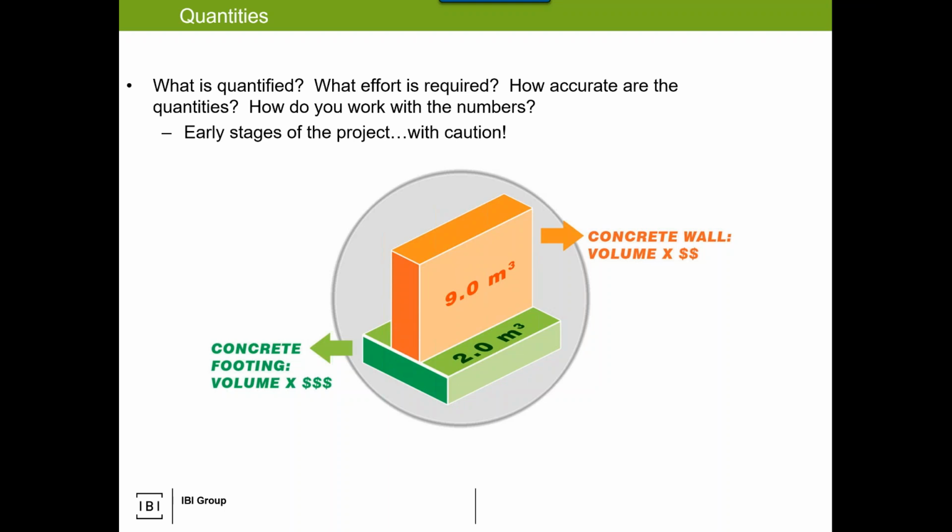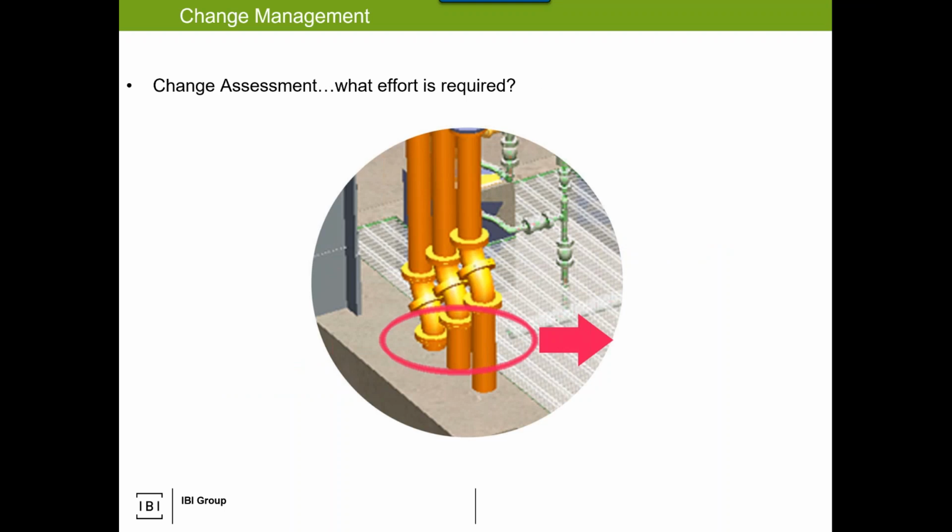Elevator pit slabs? Elevator shaft walls? Stair shaft walls? Are they bearing? Are they just dividing walls? All of these types of poured concrete would have a different cost, which is why delineating, using the Revit example, walls, floors, roof, etc., and then delineating the materiality to be concrete or not, and then further delineating some sub-parameters to allow us to quantify in different mechanisms is heavily valuable.